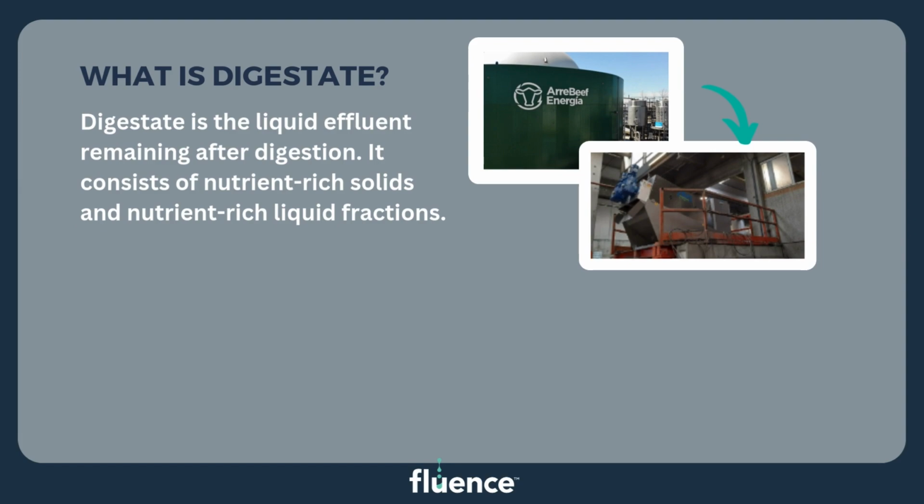So what do we mean by digestate? Well, digestate in simple terms is the treated effluent that's discharged from the digester process. Recall from our digester tech talk that we discussed the types of digester projects. These can be regional food waste, manure-based, specific individual industrial wastewaters, or municipal biosolids. So the quality of the digestate will be different between these systems. In most cases, though, digestate will contain a residual nutrient load.